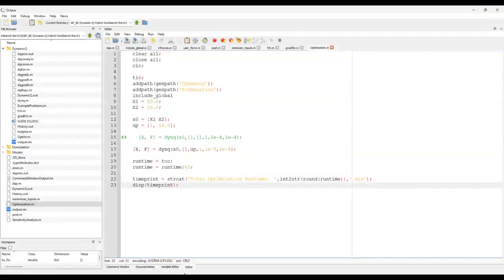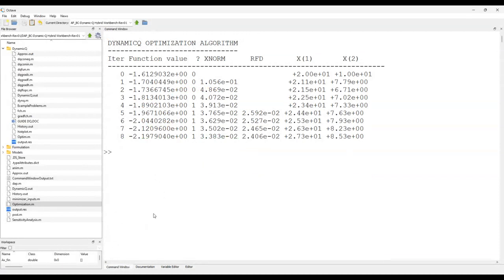So what I can do to accelerate this is change my move limit value. Referring back to the procedure that Dr. Alex Hay covered in his code addendum, he says that your move limit should be more or less the same order of magnitude as the radius of the region of interest. To calculate that, it should be the square root of the number of design variables, in this case 2, multiplied by the max variable range. So in our example, that would be, let's say, 50 Newton meters.